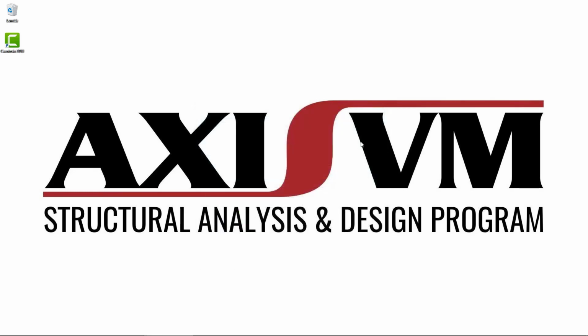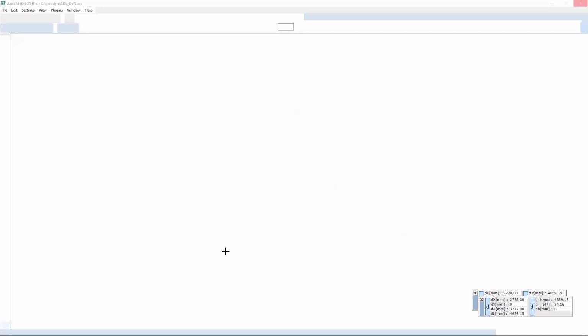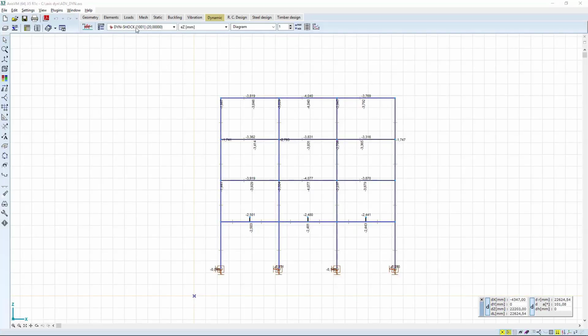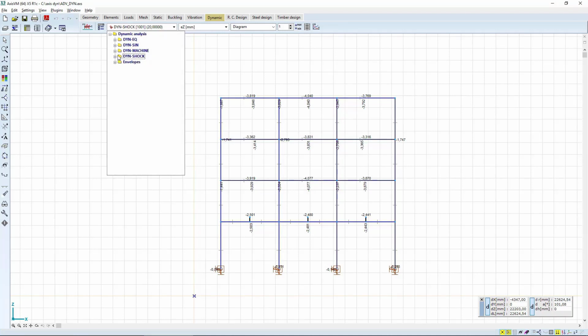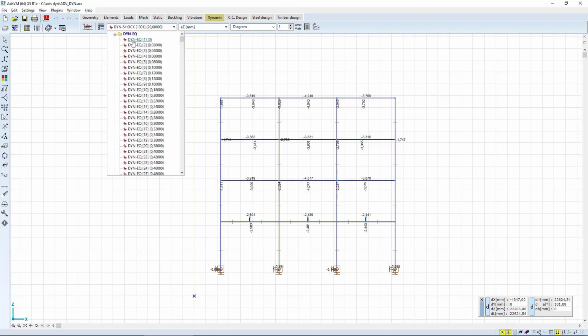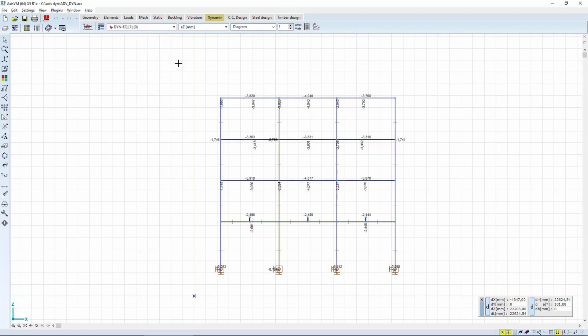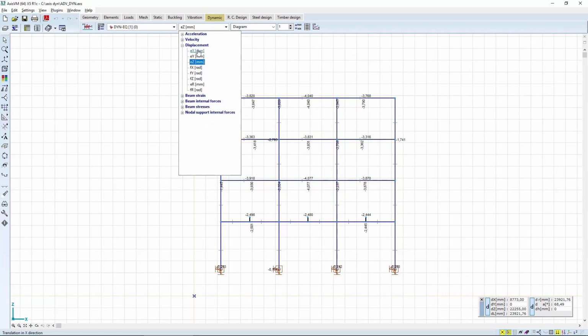The results of each time step are put in separate cases denoting the time step, time, and the load case of the result. In dynamic tests, the result components are supplemented with speed and acceleration data of the nodes. A specific time step can be selected from the drop-down list. Note that each dynamic time step contains the results of the combined effect of the set static and the dynamic load cases. An animation can be made to present the dynamic results.